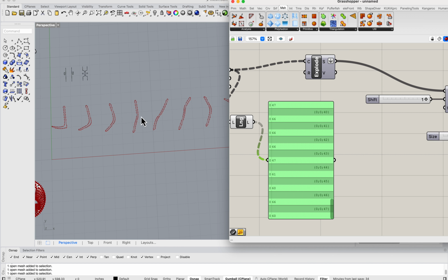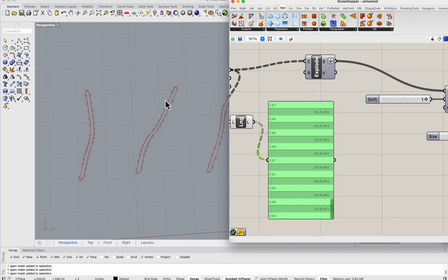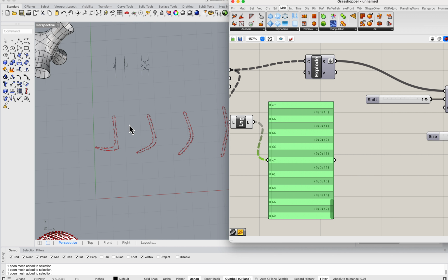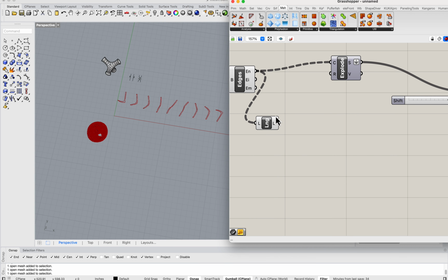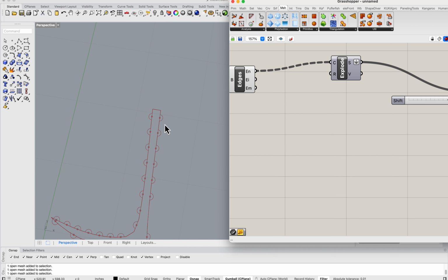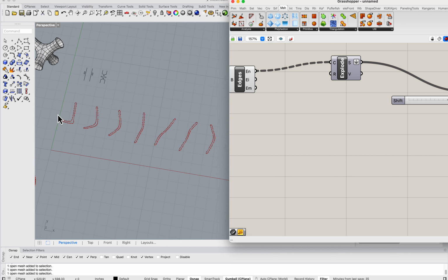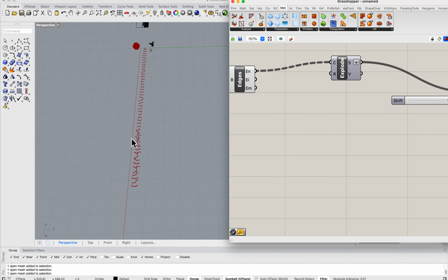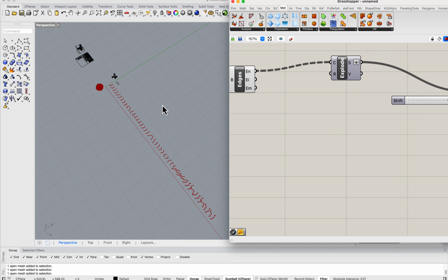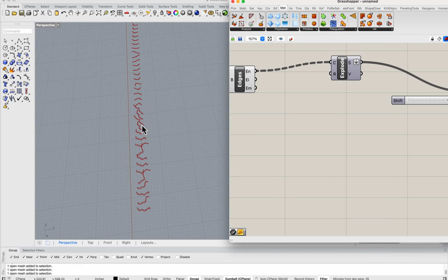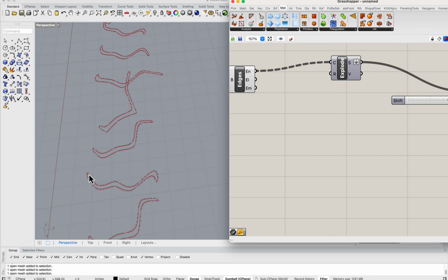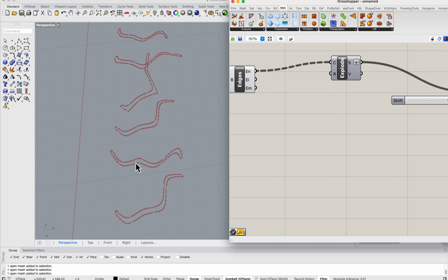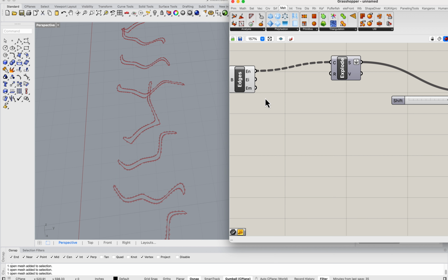So you might have to do some manual operation, but the scripts can help you build these sorts of detailing along the boundaries. So maybe not everything can be automated here, but at least if you process all the edges, then you can basically simplify some of them, or choose some of them. Or maybe you can bake the individual strips and put the same length ones into one code and then adjust it and process these as well, because you won't be able to fit these into the laser bed, so they have to be divided up into manageable chunks.